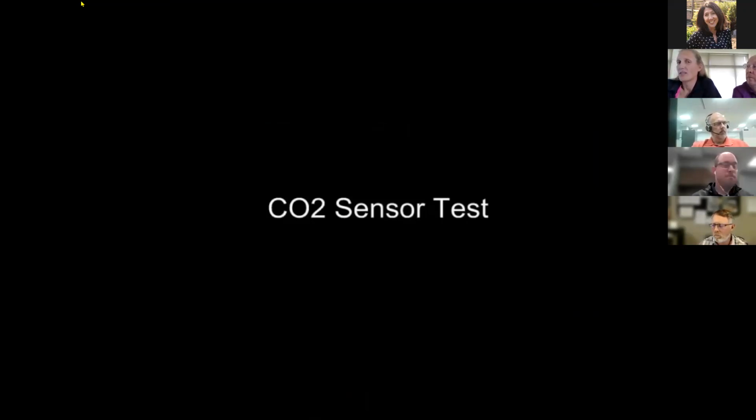So for annual or semi-annual testing, smoke is typically required. Smoke is another way to test fire alarm, and we like to use both options oftentimes because we've had many experiences where smoke might cause the fire alarm to initiate, but the key switch doesn't, or vice versa. Maybe the key switch worked, but the smoke didn't. So it's always nice to test the sensing tubes as well. Any questions?